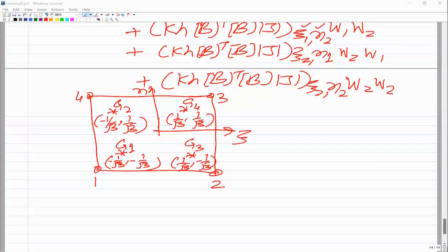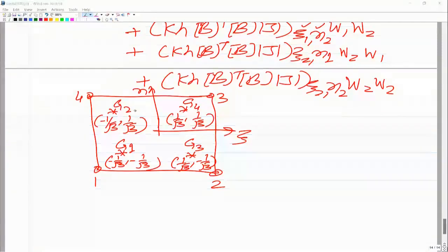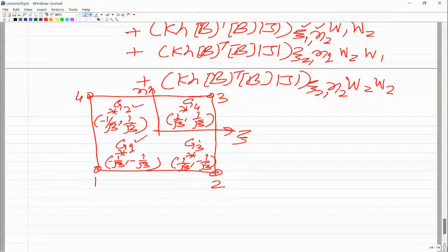Another significance of these Gauss points is that when we do the finite element calculations, the stresses are accurate at the Gauss points. They may not be accurate at the node points. Of course, if you use a very fine mesh, a very large number of elements, then the stresses would be accurate at node points as well as at the Gauss points. But if you just use the optimal number of elements, which gives you the converged result for the displacements, then the stresses would only be accurate at the Gauss points. So that is at these Gauss points G1, G2, G3, G4.